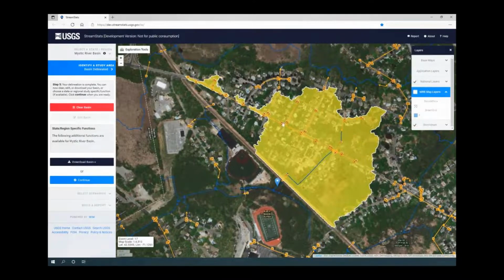you'll see that some of the flow upstream is surface flow, but much of it is also catch basin flow from storm drains. And you can also see these disconnected pieces of the basin. This is what you're going to see in urban areas as opposed to natural flowing areas where the delineated watershed is always one polygon. But in these cases, what you're going to see is disconnected pieces because the storm drain that makes up this flow here doesn't have any catch basins in this area.